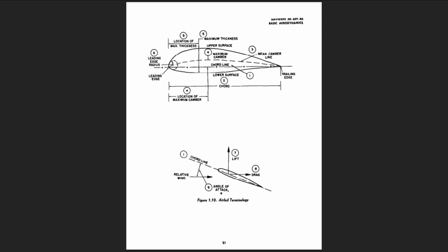Of course, it is important to differentiate between pitch attitude angle and angle of attack. Regardless of the condition of flight, the instantaneous flight path of the surface determines the direction of the oncoming relative wind, and the angle of attack is the angle between the instantaneous relative wind and the chord line. To respect the definition of angle of attack, visualize the flight path of the aircraft during a loop and appreciate that the relative wind is defined by the flight path at any point during the maneuver.